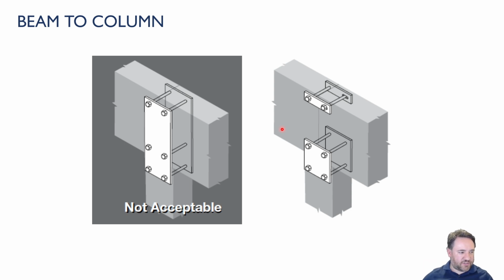Okay, so the one at the left, you can imagine why this is not acceptable for the same reasons that we just talked about, because here we have two bolts which are separated by quite a large distance, but the steel plate restrains the movements of those bolts. So those bolts will always be that exact distance apart. So then if the beam behind wants to shrink or expand, it's going to induce perpendicular to grain stresses, which could cause cracking of this beam, which would not be desirable.